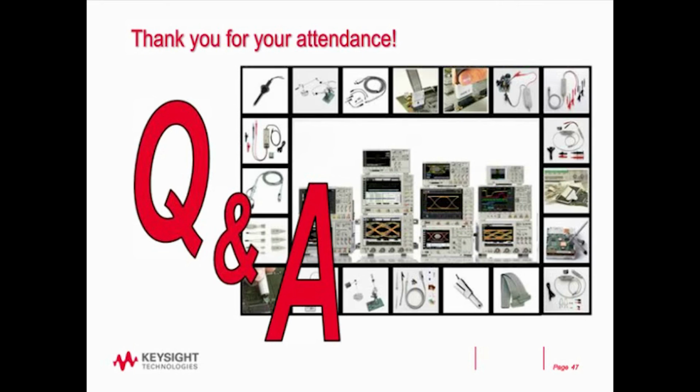Now, if you're trying to measure the highest frequency possible coupling or noise, or perhaps switching noise that's in there, you may want to open it up all the way so that you can see your highest frequency. Now, something I didn't mention is, we talk about a switching frequency in the case of our demo board that we use for some of our hands-on workshops. It's only switching at 70 kilohertz. But if you run an FFT on that, you're going to see you have multiple harmonics of that 70 kilohertz that go up to much higher frequency. So there can be frequency content due to the switching that's going on far beyond the actual switching rate.